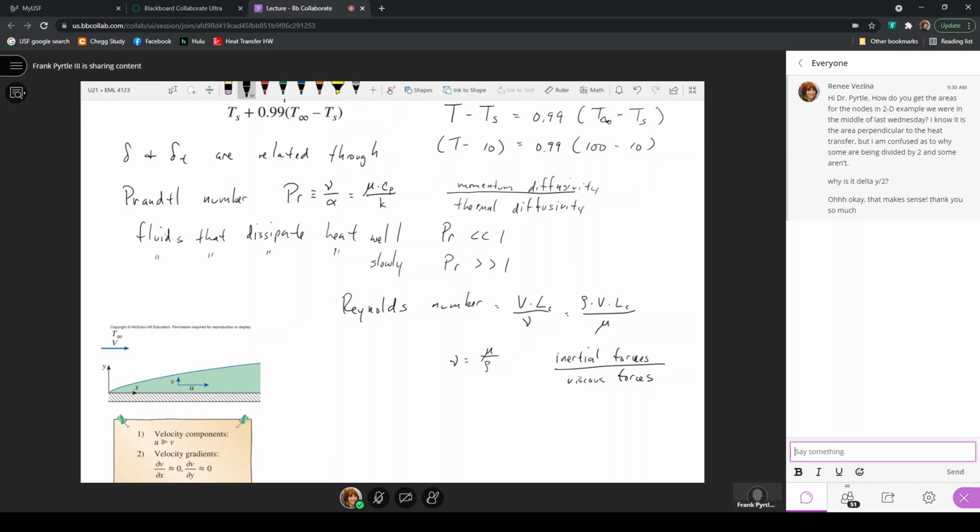And depending on the kind of calculation you're making, it may be a Reynolds number based on a local value, calculated for the determination of something like a local heat transfer coefficient, or for an average heat transfer coefficient.